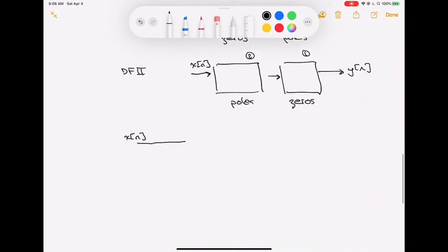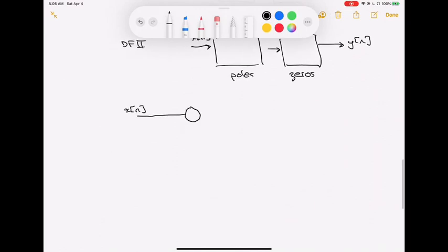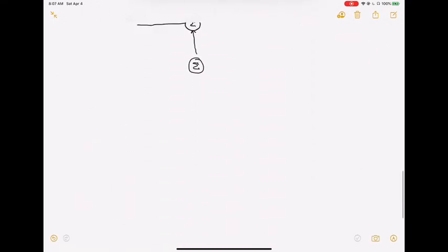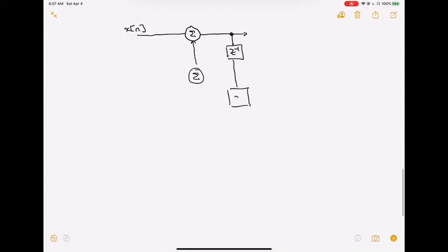So I'm going to go back to this guy and run it into a summing node, right? So we're just interchanging the order of these two blocks, and that came from another summing node down there. Then we had this thing keep going out, and what did it do? Let's grab a delay by 1, and then we're going to delay again, right? And then we have these feedback paths with their gains. So here was the gain minus A1, and that got fed into this summing node. And then over here there was another gain, minus A2, from that summing node as well.